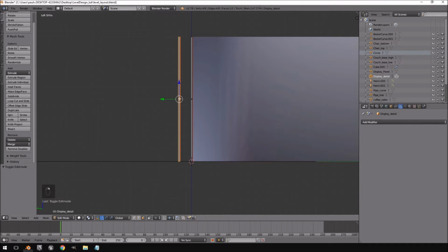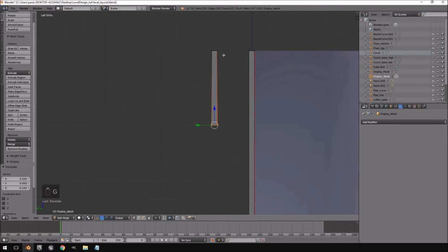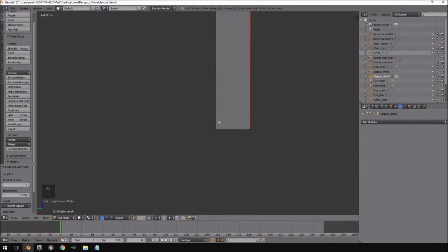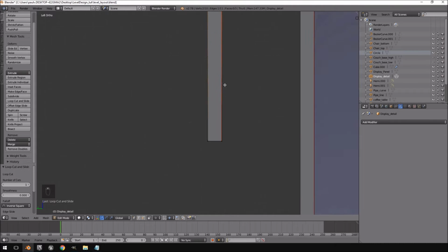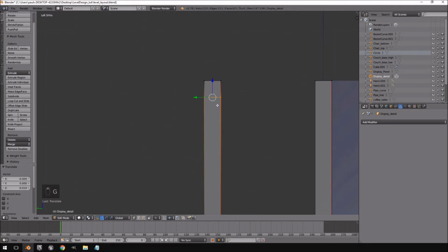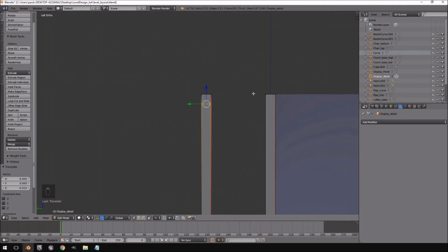Essentially, with this piece I'm going to select it, go back into my vertex select mode, and I think I'm going to shrink it down, bring it up by pushing G and then holding Control and dragging it up, to roughly about there. Then I'm going to push Control R and cut it. We have a width of 3 units, although because we're at a strange angle, I'm just going to bring it down like that. So we have a width of 3 units for this piece over here.